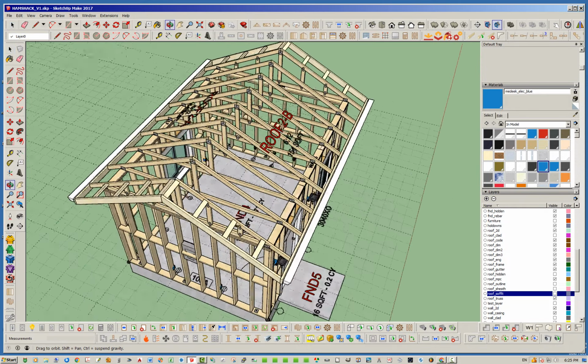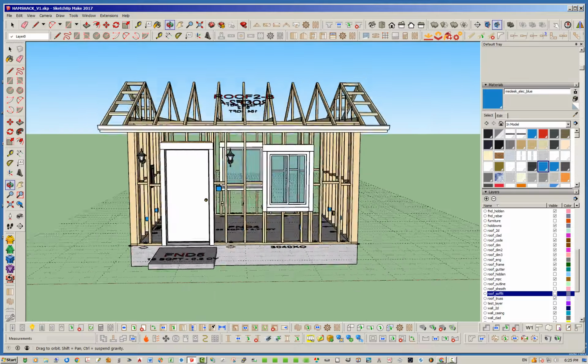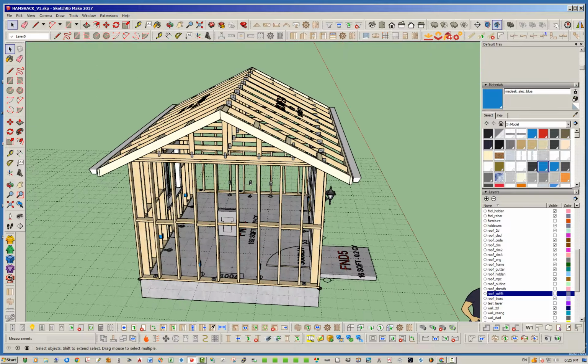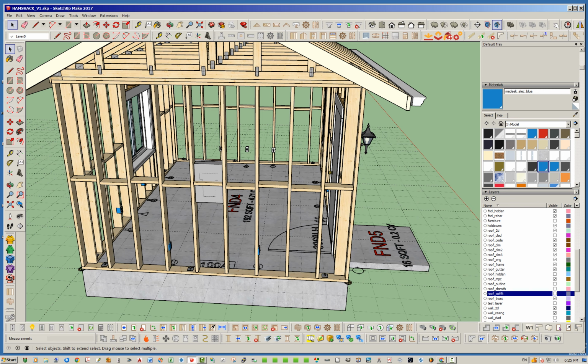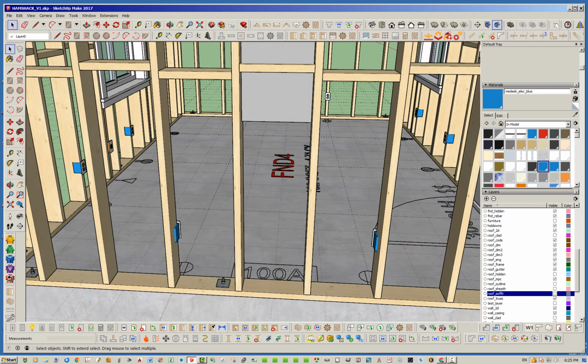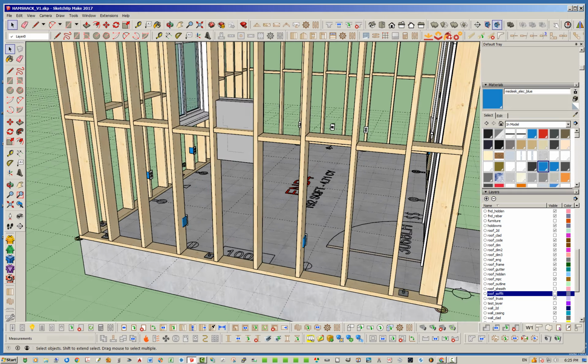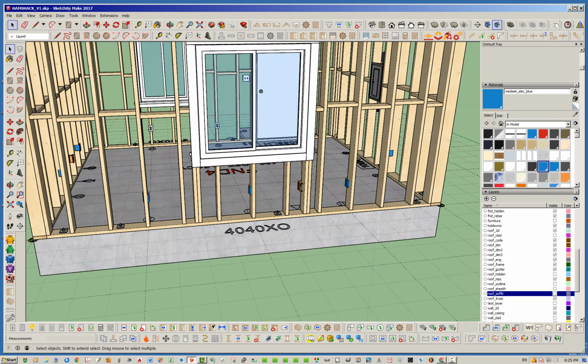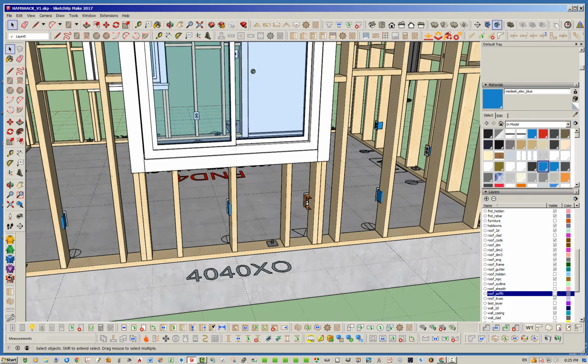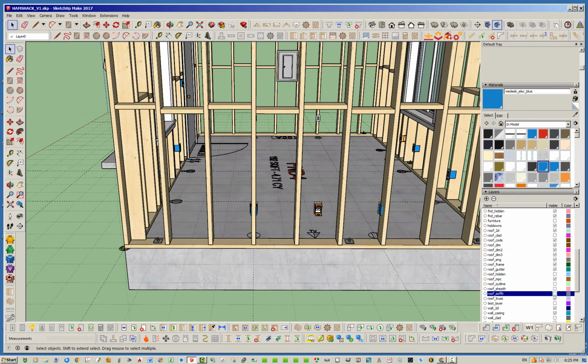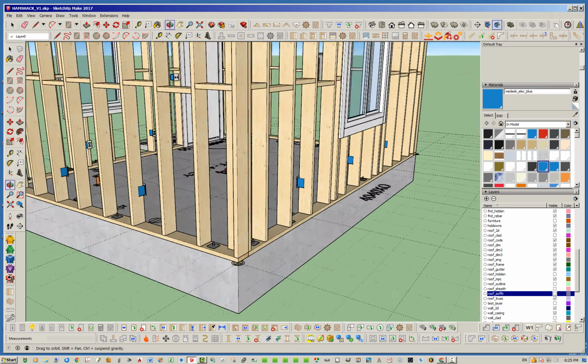So that's pretty much it as far as the general structure. You've got all your studs, you've got everything in there. And actually when you take away all the sheathing and cladding, you can see where your outlets are landing. These are going to have to shift a little bit, but that's not a big deal. You'll notice they all center up on the studs, except this guy sitting out here. If we do want this centered, we can always put in a block or two, and so we can position it that way.